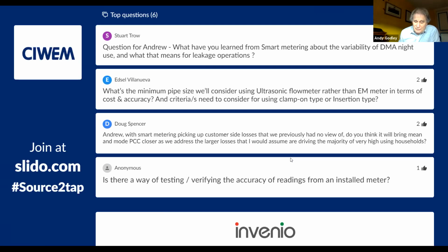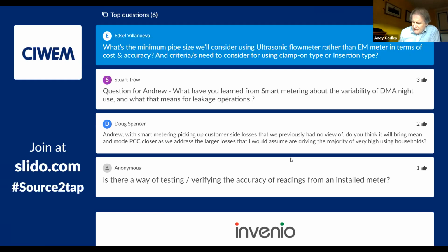The other half of that question was around mineral deposits, wasn't it? Not specifically, I think, is the answer to that. We haven't specifically looked at mineral deposits on electrodes. Again, the fact that we haven't looked at it suggests that it's not a huge problem. We've done some work around fouling on electrodes, but typically, again, wastewater applications where fouling is more grease, fat, that type of thing, which will disrupt the signal path and will disrupt the measurement.